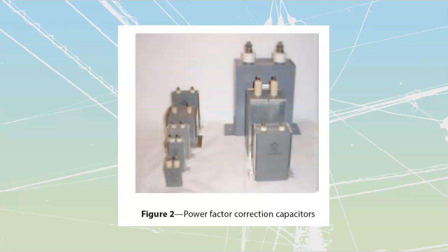And then the next bit is a set of calculations where they go through and say, what would happen if I use a cap that is rated for a different frequency? So they have a 60 hertz cap that they're going to use on a 50 hertz supply. That's the example that's given inside of there. I'm not a particularly big fan of that example because I don't have 50 hertz systems. Here in North America, we are running a 60 hertz system.